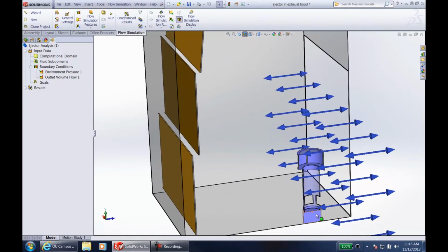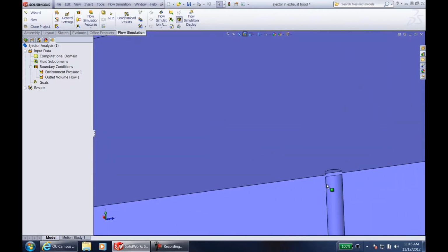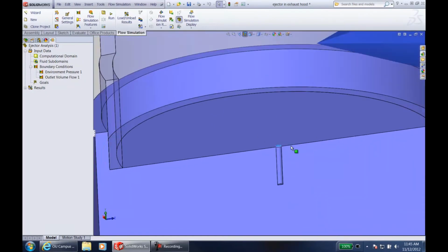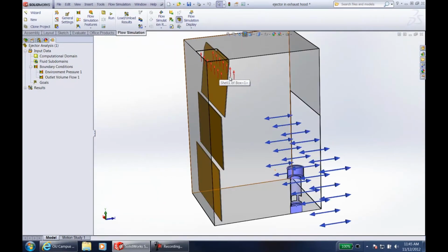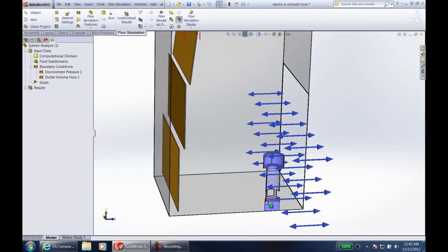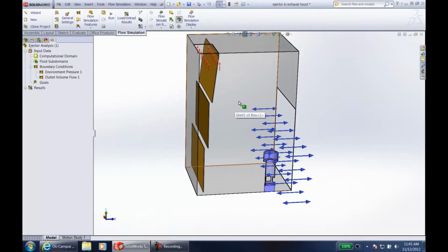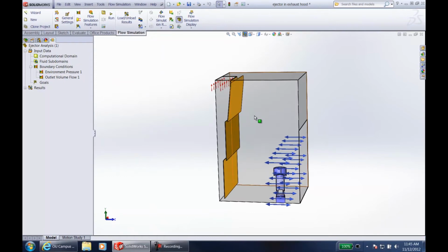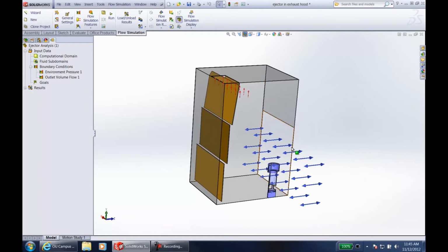As you recall also, the problem statement here is resolving this very small injector nozzle surface area in the overall computational domain, which is much smaller than other flow channels and the overall computational domain size. Then we discussed that by resolving this, we would also excessively resolve, with too many mesh elements of too small size, the rest of the domain, and how to control that.